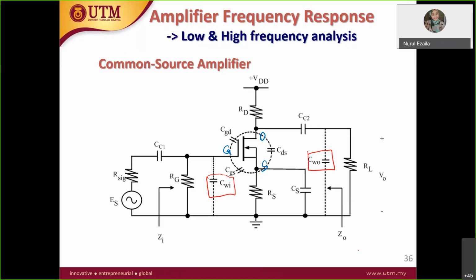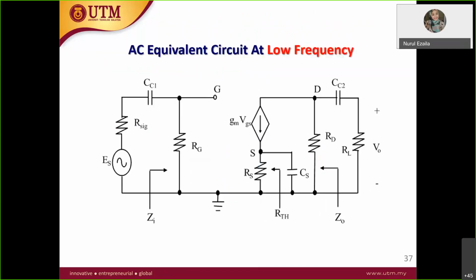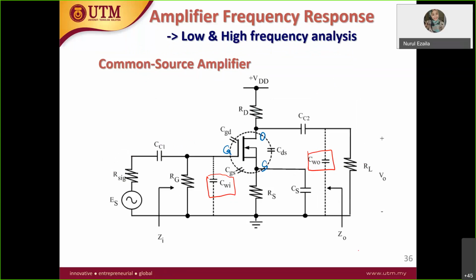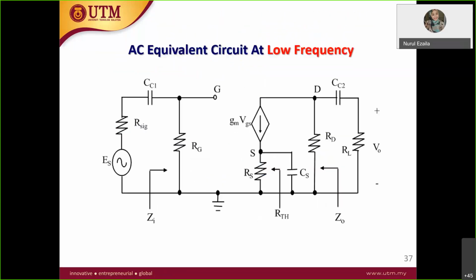So let's take a look at the low frequency. These are all the capacitors. If you want to analyze the low frequency, the CGD, CGS, and CDS are ignored.